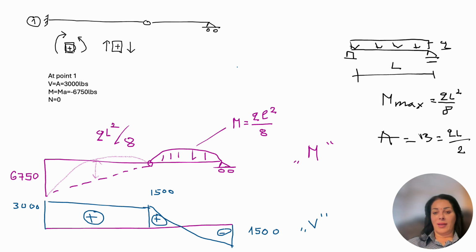In strength of materials, the addition is that you will have some cross section. You need to determine the centroid and moment of inertia, and the state of stress will be due to bending. You will have sigma equal to M times c over I, and your transverse stress will be V times Q over I times t. So this is the part which I wanted to cover today.